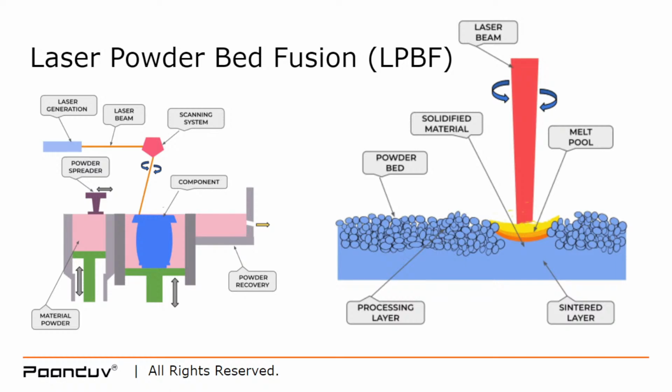So if you especially focus on the right image here, you can see the powder bed, and then you can see the solidified material under the laser. Then there's a melt pool, which is just created when the laser hits the powder particles.